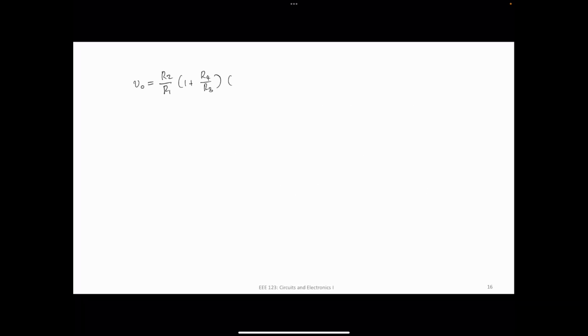Okay, so finally, what is V sub O? V sub O is R2 over R1, and then I'm going to get 1 plus R4 over R3, times V1 minus V2.